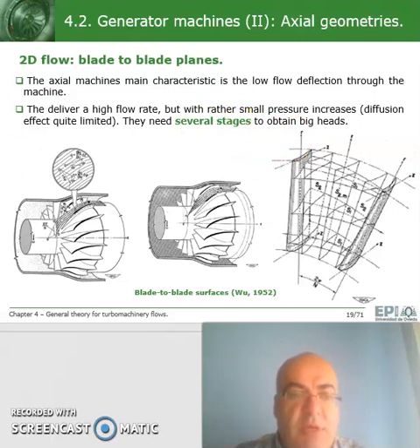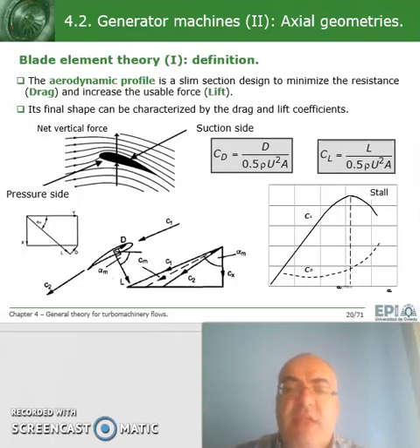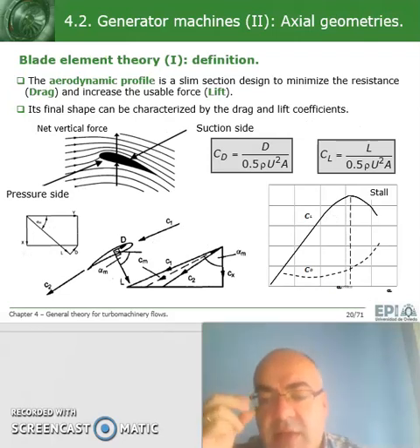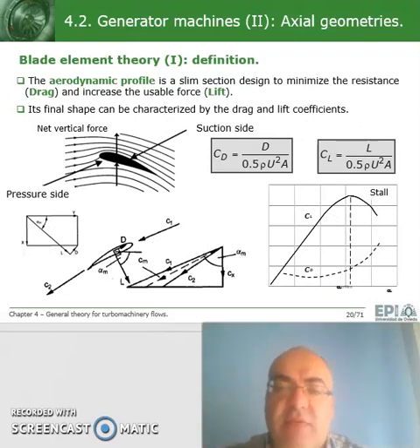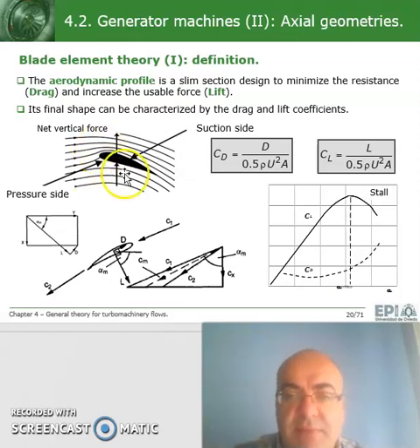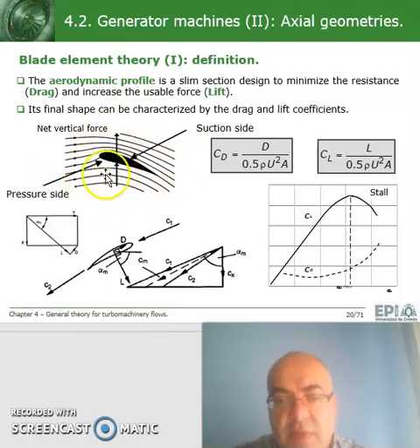Another possible option, also developed in the bibliography, is to go back to the basic fluid mechanics ideas on the lift and drag coefficients. Typically we have a profile like this. The turbomachine is divided into different blades, and the blades are in fact a stack of aerodynamic profiles, and we could for instance study the pressure and suction surface and different features of the aerodynamic performance.